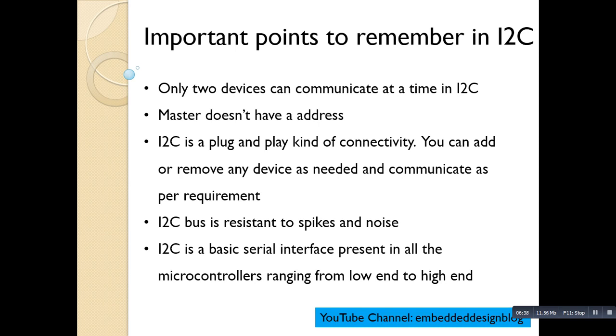It is hard to pick a microcontroller without an I2C interface, except for a very small microcontroller. So this is how popular I2C is, and there are many slaves available to be connected across I2C. These are some of the points which you have to remember while using I2C.